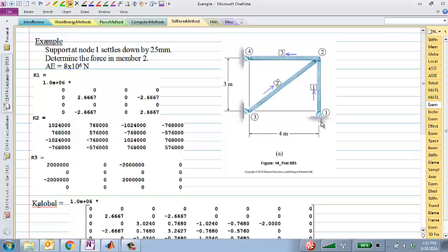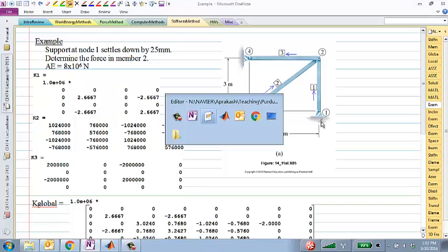It won't, right? No, because the local force displacement relationship is oriented along the x prime, y prime direction, and the x prime, y prime direction coincides with global xy only in this horizontal configuration. If I have an element in the vertical configuration, the x prime, y prime is oriented like that, which is different from the global coordinate system, and we'll easily verify this.